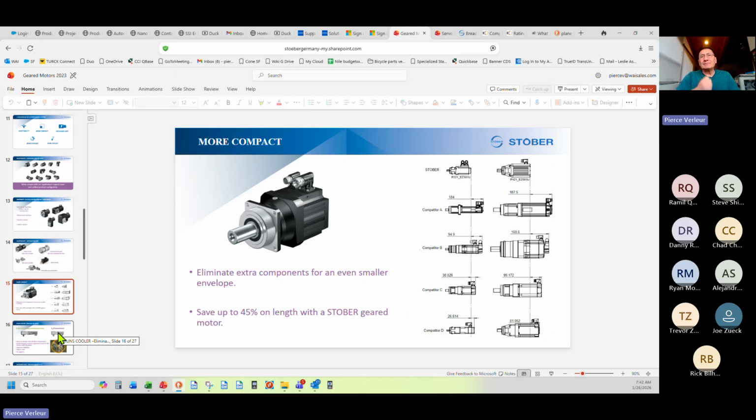Obviously, in a dynamic stop, you have a whole lot more energy because you're dissipating the reflected inertia of the load in the gearbox and the motor when you clamp the brake on. A holding brake is applied only at zero motion, and it does what its name says. It holds things in place.